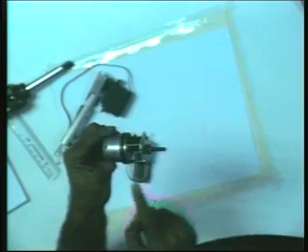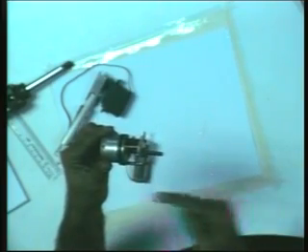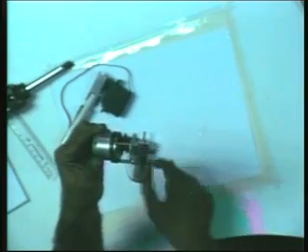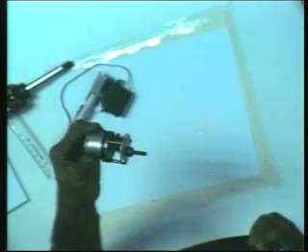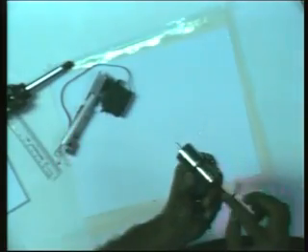So let's go back to the... Here is one gearbox. It's a conventional gearbox fitted onto a motor. No, it's not coaxial. Many a time, if you want coaxial input and output, where the motor shaft is in line and the gearbox output is coaxial, then you use what are known as planetary gearboxes, as somebody had mentioned, or you could use what are known as harmonic drives. It is important that the weight of the gearbox be as low as possible when you use it in robotics. You don't want to lift gearboxes, you want to lift a payload.